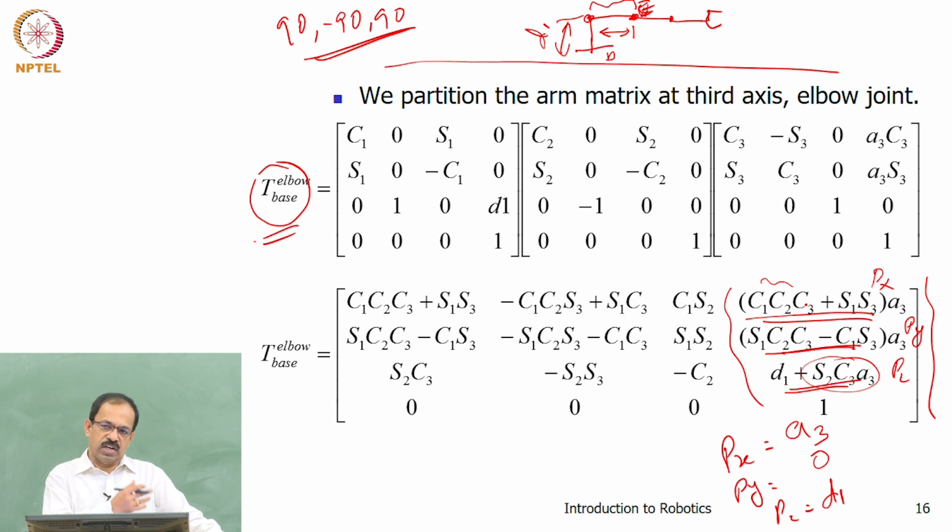So your angles, whatever DH parameters you assumed and the coordinate frames you assigned, everything is perfect, and that is why you are able to cross check your formulation. So this way you can make sure that your formulation is correct. Whenever you do a forward kinematic relationship, in the first 3 joints you do it first and cross check whether you are getting it correct and as per your home position, then you are able to verify it, and that will tell you that you are correct.